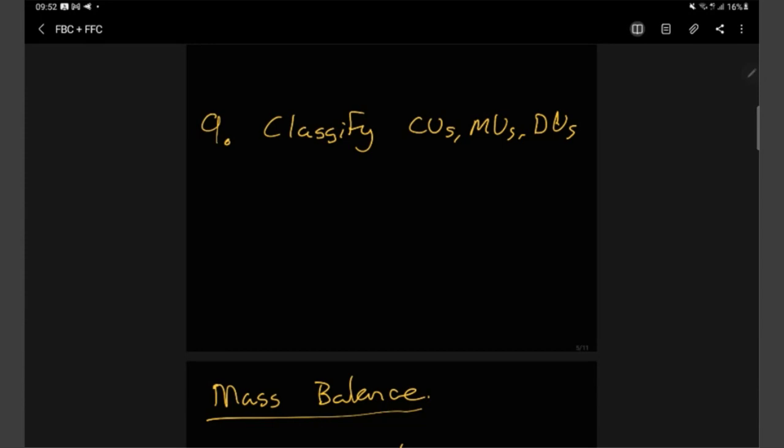The manipulated variables, we don't always just specify because we want to. There are means and ways of analyzing which variables are best to control a specific controlled variable. We'll get into that in process control next semester, but it's not always the case that we have a SISO system, a single input, single output system. If you have a single input variable, obviously that variable must be the one that you try to manipulate for your single output, your controlled variable.